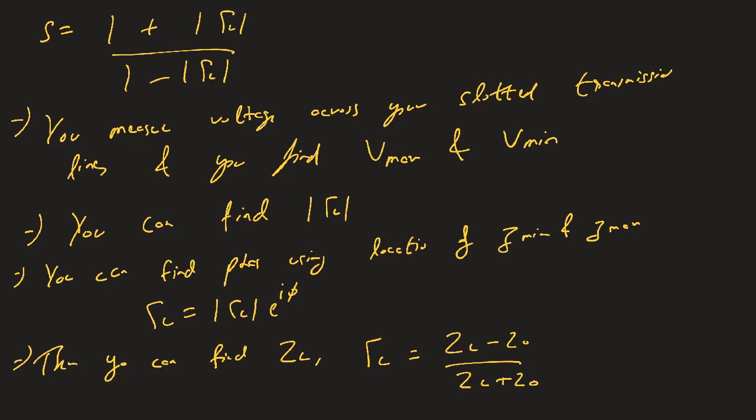Ask yourself, how is this voltage linked to the integral of the electric field from some reference point to some point R? What does V of R mean? What does V of Z mean? Ask yourself, how are these electromagnetic waves propagating within these conductors? We've done a proper wave treatment, so we know that you only get appreciable penetration as far as the skin depth of the conductor.